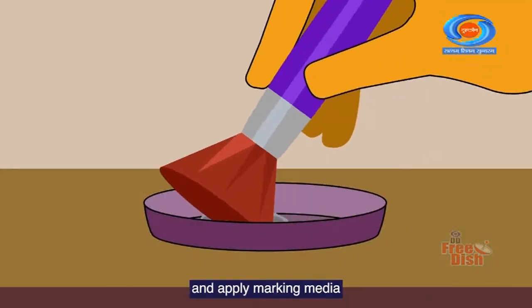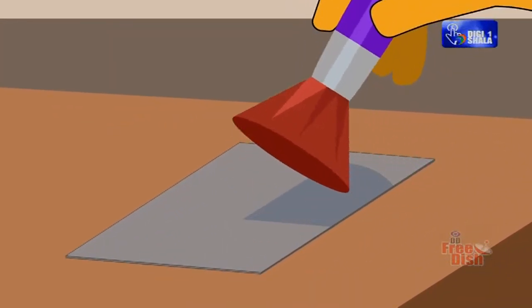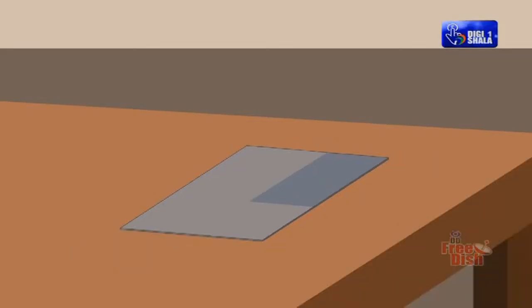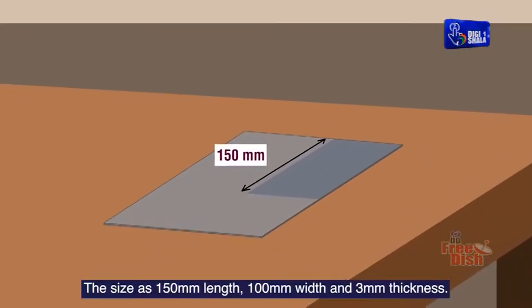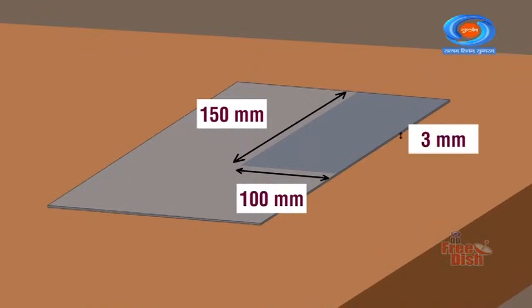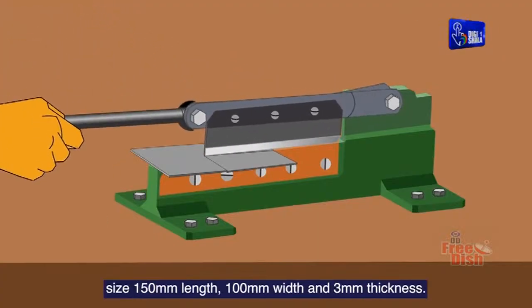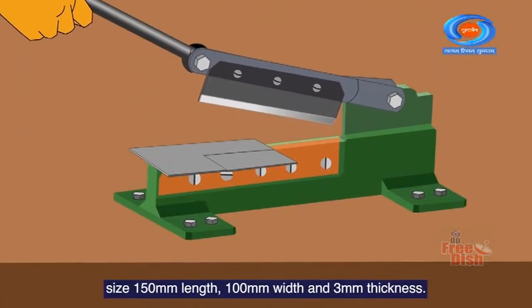Take an MS sheet and apply marking media. The size is 150 mm length, 100 mm width and 3 mm thickness. Cut the MS sheet as per the size, 150 mm length, 100 mm width and 3 mm thickness.